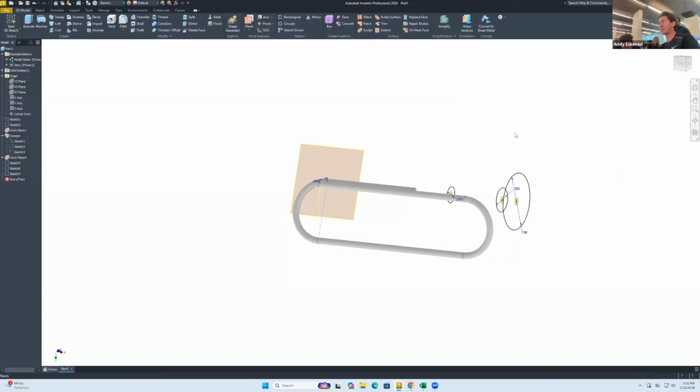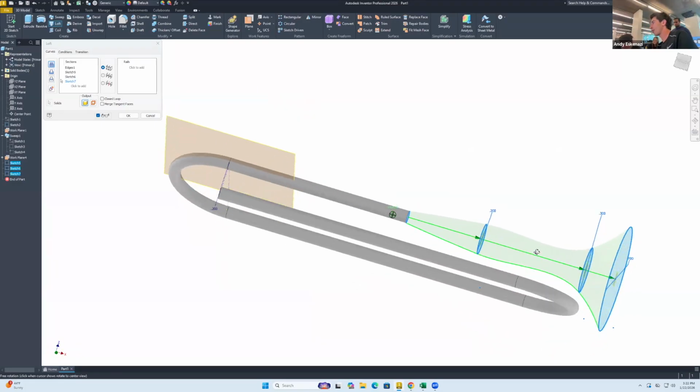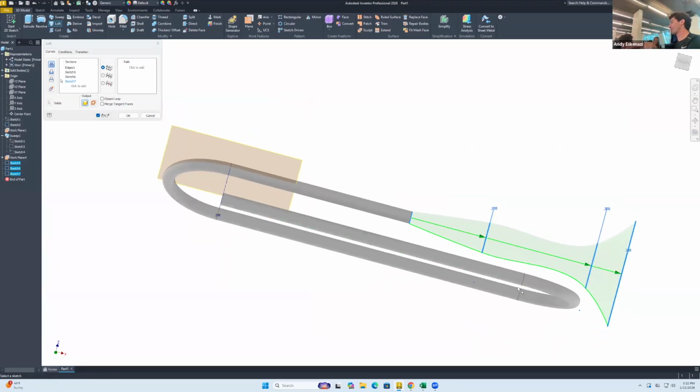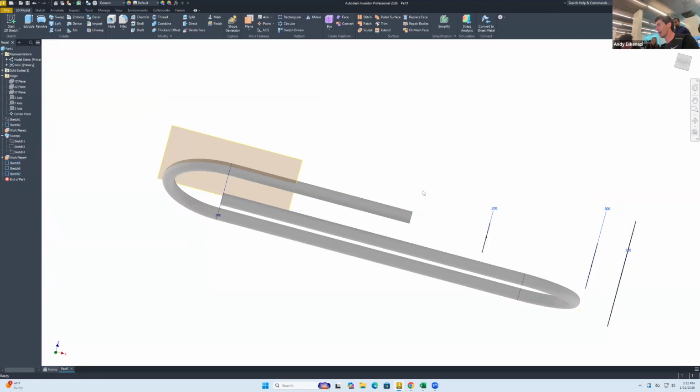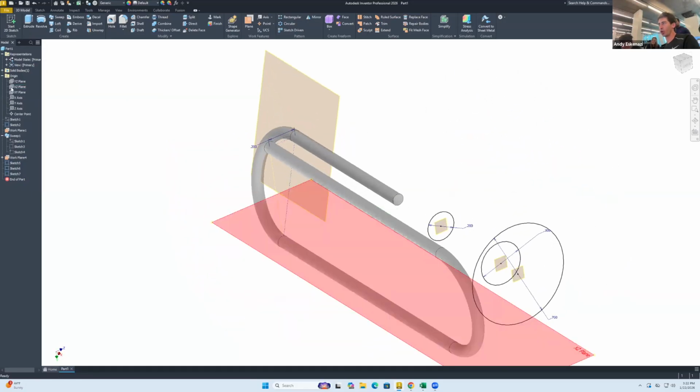Okay, so now finish. We go here to this command that's called loft. Loft will prompt us to select all of these profiles that we just designed. So now we can go here to face, 2, 3, 4. Now, what's going on in here? It looks kind of ugly, doesn't it? So how do we modify this stuff? Well, it's not difficult at all. What we have to do is create a new sketch on, let's see what's convenient. So I have to create a new plane.